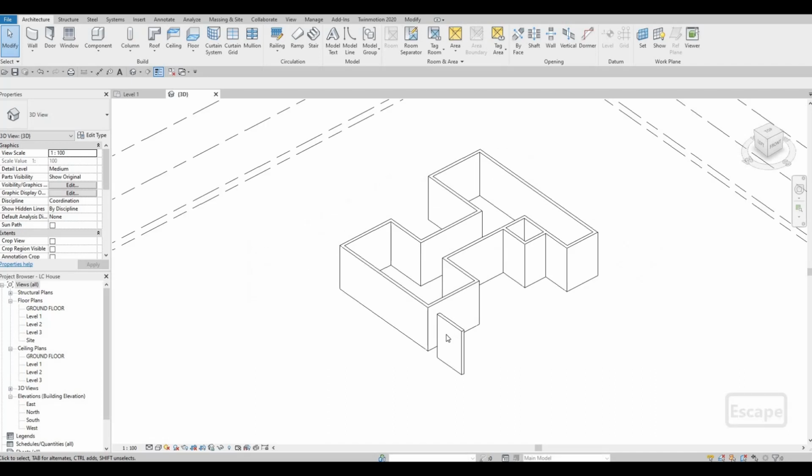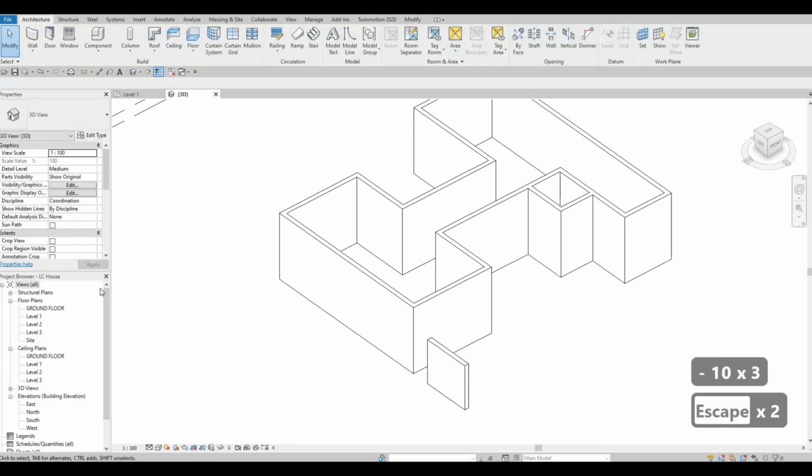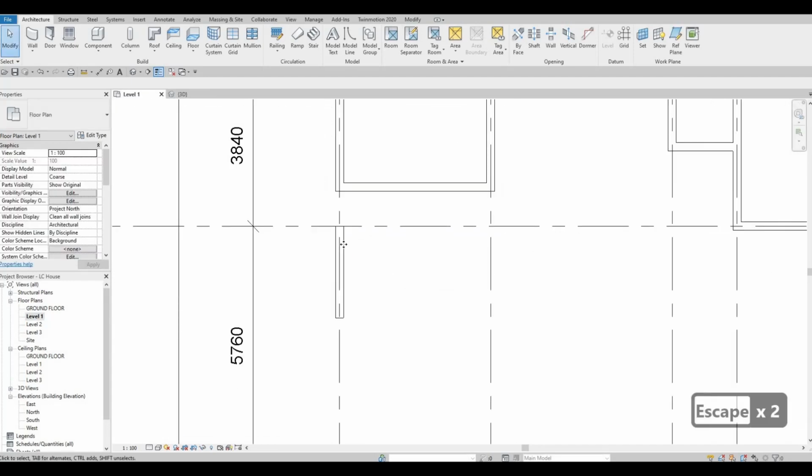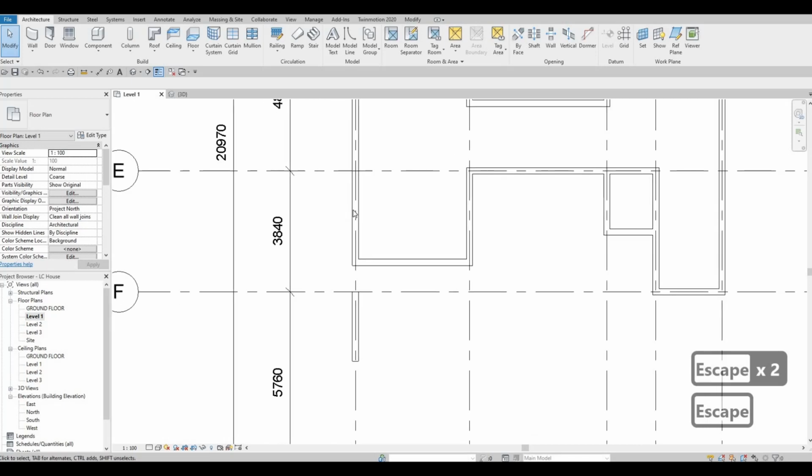I just want to make this one a little bit small. So maybe around 1500 from top offset, but it needs to be maybe -1000. I think that's good enough, and it will maintain that height. And then if we're ready, we can extend it to ground floor.